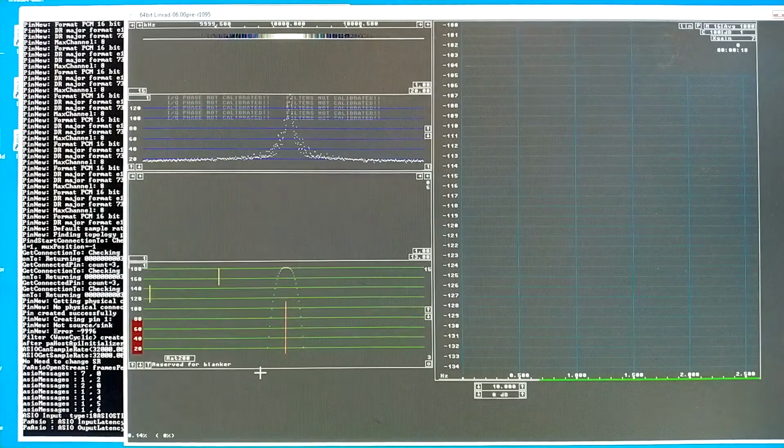Looking for the phase noise at 1 Hz offset is a very slow process. I have to wait about 6 hours to get a reasonably stable value. I don't know exactly what the error is, but several tenths of a decibel. And then when comparing two different values, the total uncertainty becomes unacceptably large.